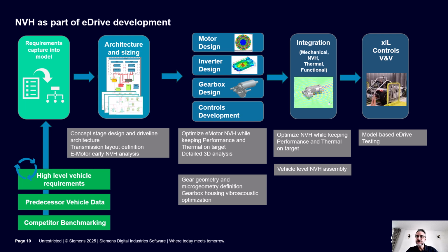Finally, in the last stage, we will start doing more and more testing, although testing will support the whole process from the start. But here we start to have the system available for testing. We can do also model-based testing, including simulation model and physical system. And we will look at the performance. We can also predict the noise and experience the noise in a NVH simulator. We can do sound quality analysis and also controls fine-tuning, looking at the NVH impact.